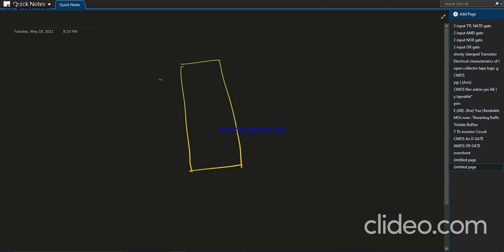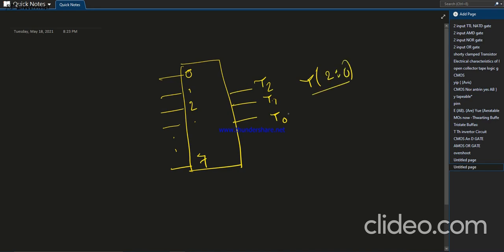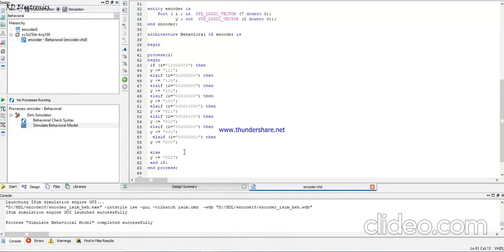input information to the corresponding code, for inputs 0, 1, 2, 3, 4 up to 7, with 3 active high outputs named y2, y1 and y0. So the signal y2 to y0 is the 3-bit output, and the information bits are I7 to I0. This is the 8:3 octal to binary encoder. This is basically the encoder circuit.